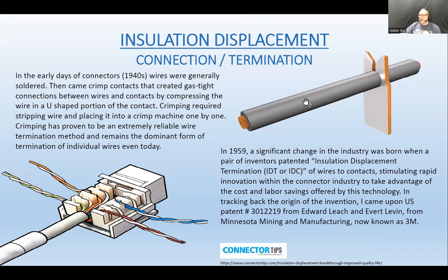Right. Now, there's one thing that I left here. I thought about correcting it because I found this picture on the internet. Here's your reference. Somebody put that as a stranded type of wire. Insulation displacement connection is not for stranded wire. If you do that to the stranded wire, some of the strands might be broken and you're going to lose the thickness of the cable. You're going to lose the specifications of that conductor. That is for solid conductors only. Whoever did that, it's a good idea to put this thing here, but I left it just so I could mention that.